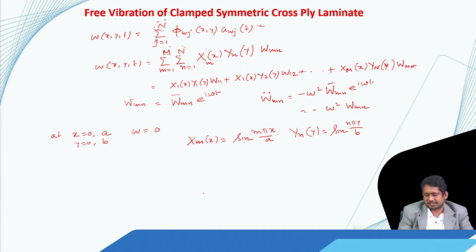We know that this kind of approximation satisfies the natural boundary condition also, because the laminate is simply supported, and also because we are neglecting I_1, so u_0 and v_0 are not needed.